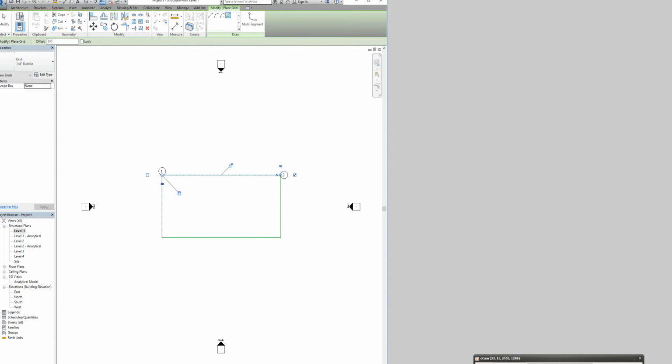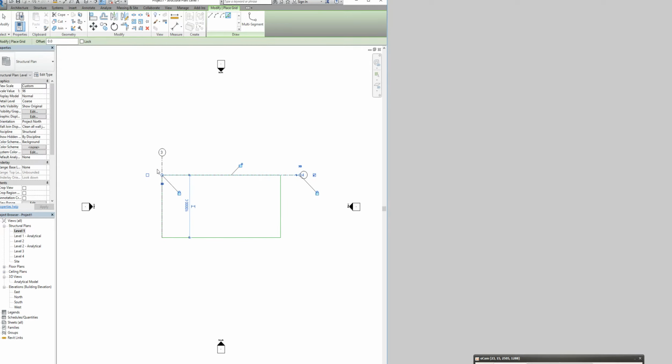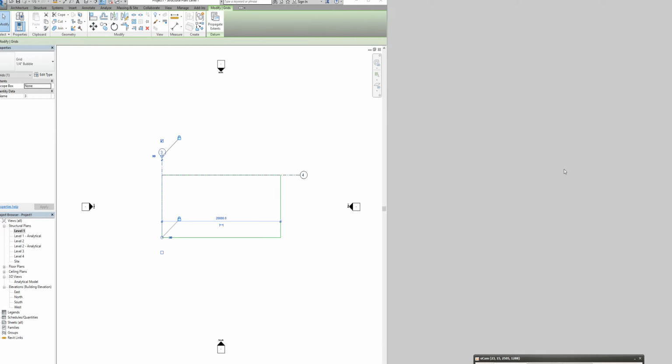Okay. Next. Select the vertical grid. So go back to Revit and just gonna extend this. This is not in the slides, so I just like to work just a little bit more organized. So just go to the vertical grid. Select it. And use array to place 5 vertical grids. I show the properties of the grid. So we just replicate that in our exercise.